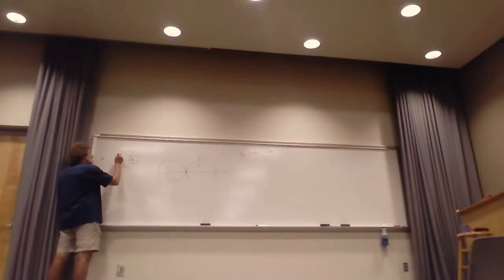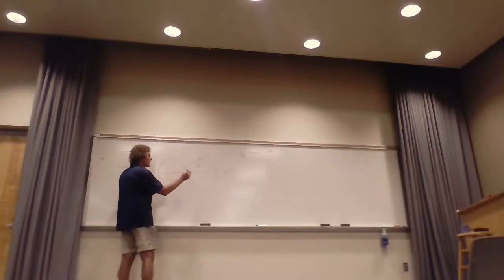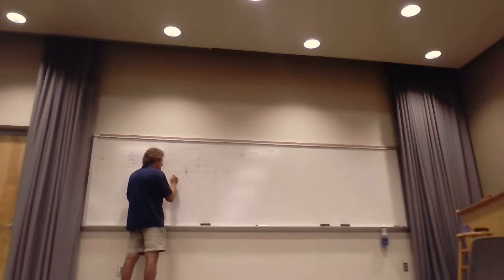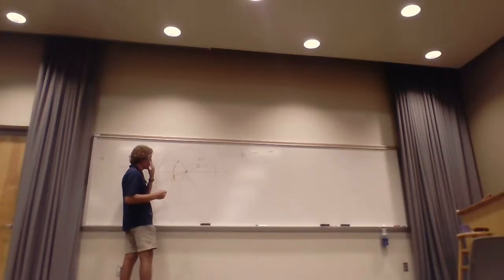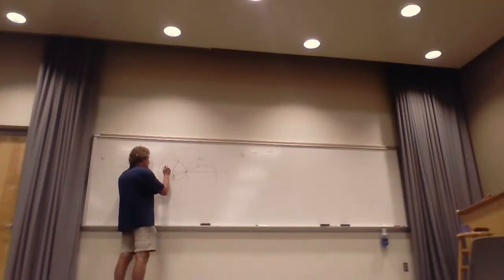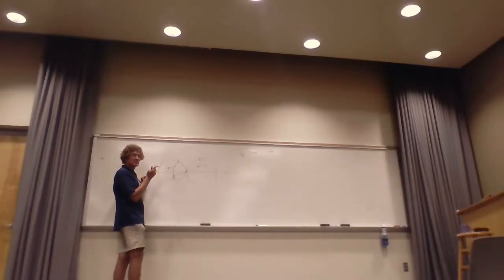So then you have to go to the admittance domain. So for here, this is your first point. We have to go here to your second point. And then I'm just going to assume we go this direction. We don't have to. We could go this way. But here you're moving along a contour of constant real value. Do you all see this? You're adding a plus j. This would be adding a plus jx, but it would be an admittance, not an impedance.